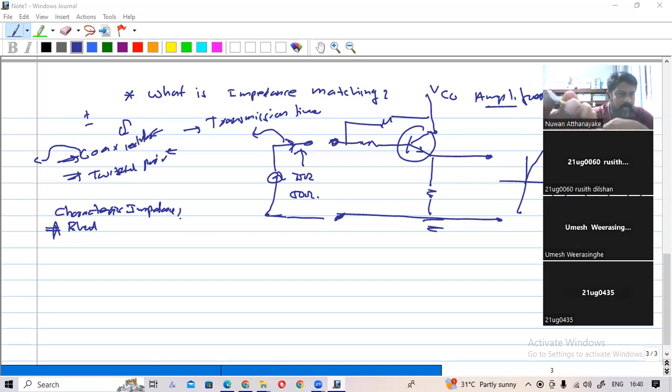So there are different types of connectors. The input impedance for an SMA connector is 50 ohm. BNC has 75 ohms and 50 ohms. But for SMA, the 50 ohm SMA connectors are there, as I know. Maybe there may be some other one also, I haven't come across it. I always come across 50 ohm SMA connectors. So that is why I told you, maybe wrong. So just have the idea.